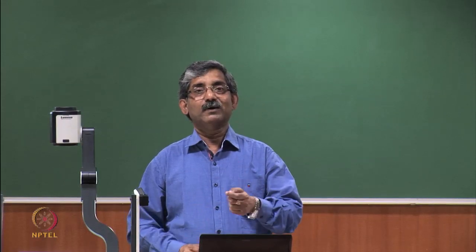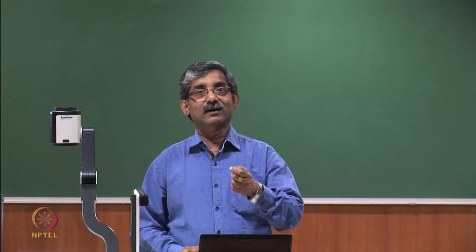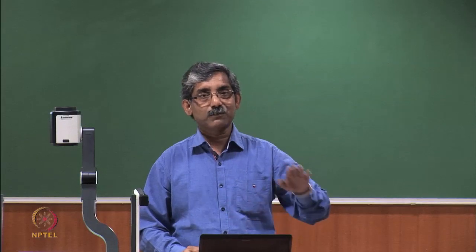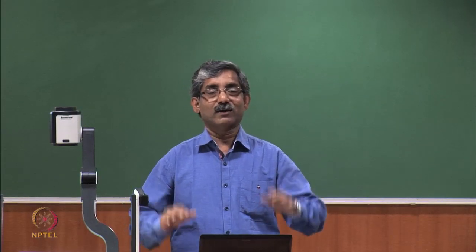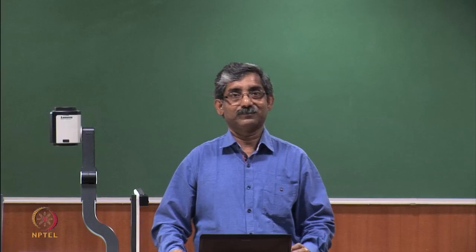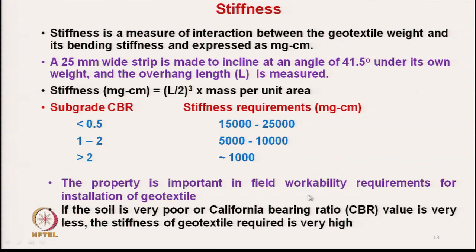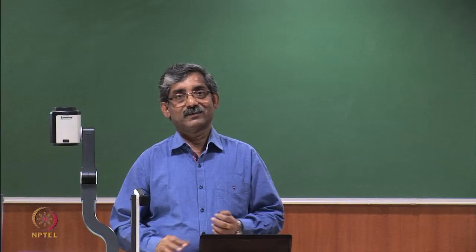We can have flexible geotextile if the subsoil is strong or hard enough. The property is important in field workability requirement, as I have just discussed. If the soil is very poor or the CBR value is very low, we need stiffer geotextiles.